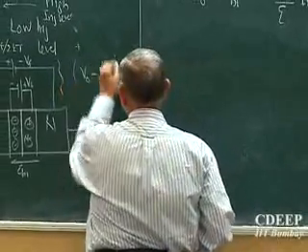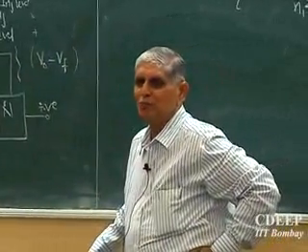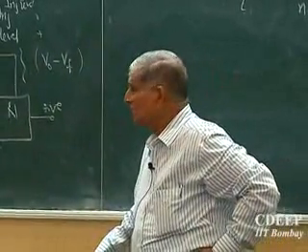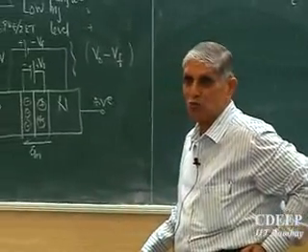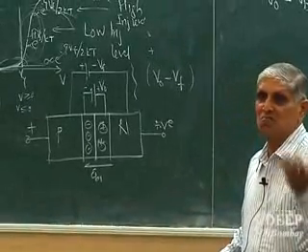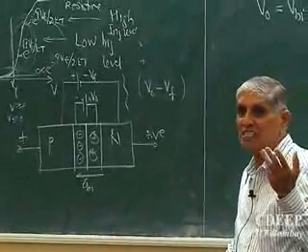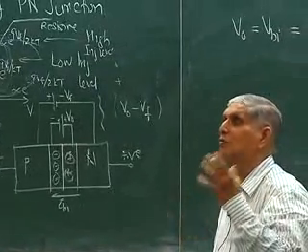Now questions could be raised before we go ahead. How much VF could it be? If you start increasing VF too much and close to V0, the currents which you will get will be as much as 10 to the power 80 or 10 to the power 90 kinds of things. By then the device will heat so much, it may not be there.